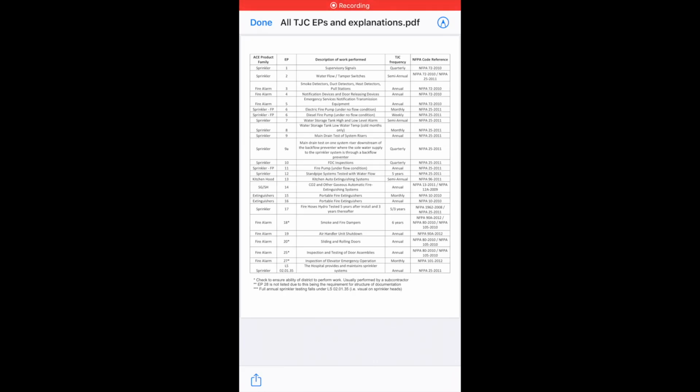In this video, we'll be creating a Joint Commission inspection for sprinkler. You'll need these EPs here, and this is what the EPs will look like. You've got EP1, which is your supervisory signals. You may have that if you have a dry system. You may have a fire pump running, fire pump supervision, loss of phase, all that. It's a quarterly test of the supervisory signals.